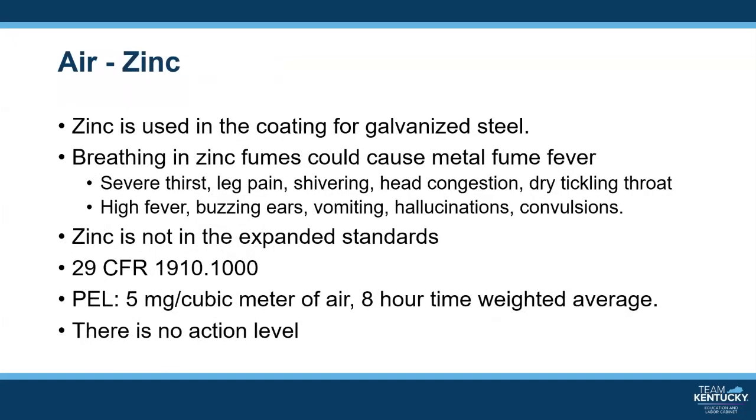Another health hazard that could potentially be in a work environment where welding is being done would be zinc. Zinc can be found as a coating material used to galvanize metal. The typical effect of breathing zinc fumes is metal fume fever. Welding on galvanized metal over a 1 or 2 hour time span without wearing the proper personal protective equipment, you may experience severe thirst, pain in the legs, shivering, congestion in the head, dryness and tickling of the throat, and a cough.